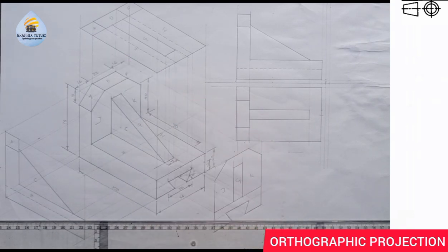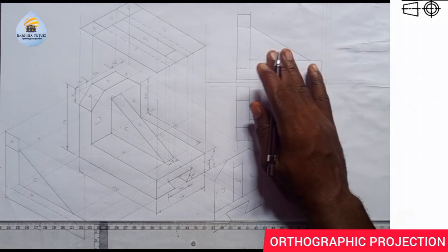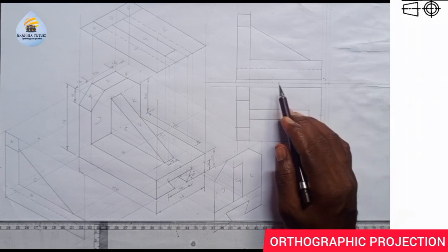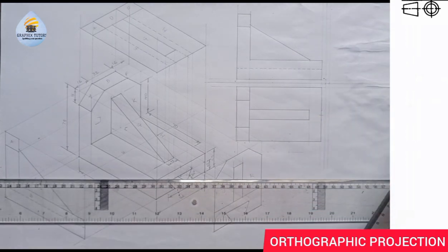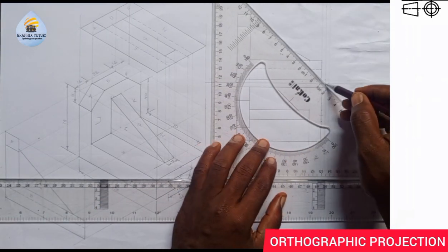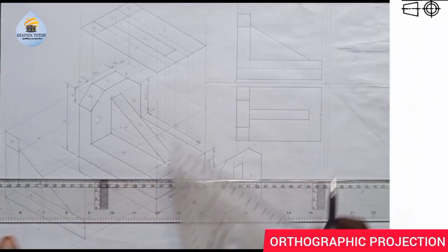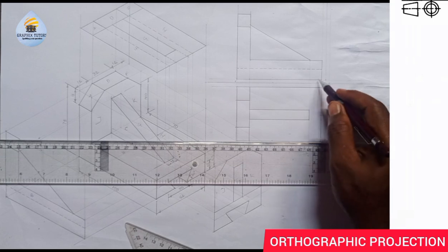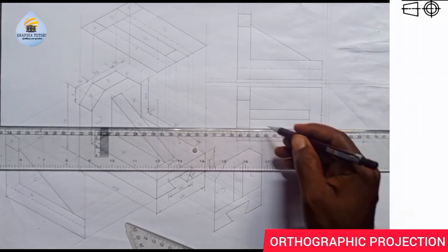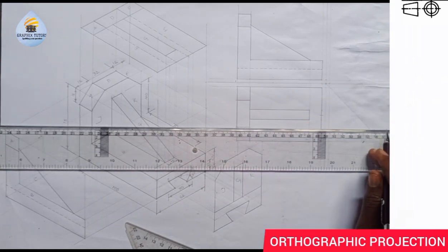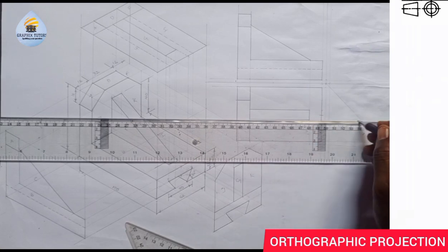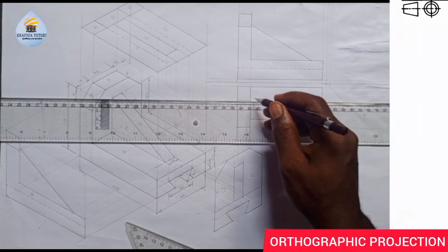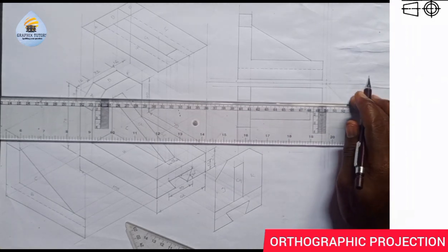Now the next thing is the end view. The end view is always beside the elevation. So the elevation is just the central part of the entire views here. So I'll come here and take this here, and I'll project all these points to meet the diagonal line at an angle of 45 degrees here. So if you begin here, take this here, take this here, take this here, these two, and we have the other one.